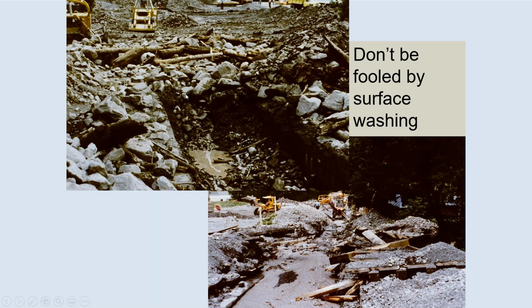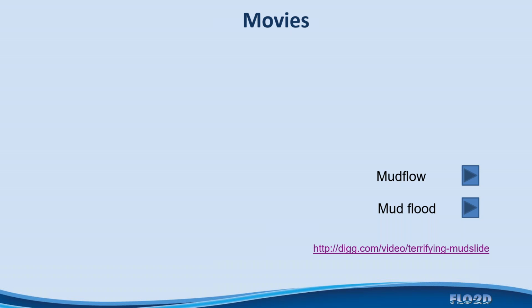And then I don't want you to be fooled by surface washing, which might occur after a mud debris flow, quote, event. If you go in and actually excavate this, you may see the mud flow material underneath, but the surface material has become washed by repetitive surges of water flow during the falling limb of the hydrograph. So I want to show a couple of movies to further highlight the delineation between mud flows and mud floods.